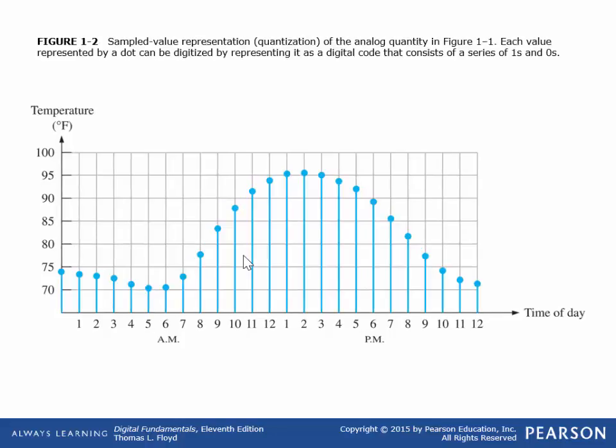So as we look at the slide, this is showing that we have certain values right here. We don't have the values in between. And the other thing is we sample. So this is the sampled data right here. And we're also going to end up with usually an integer number representing this analog value. It's going to be an integer binary number made up of zeros and ones.